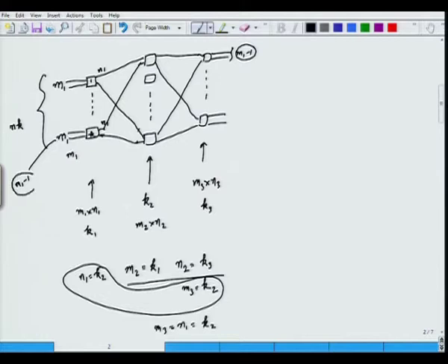the same is true at this place, that M1 minus 1 lines are occupied here. There is only one line which is left in which I am interested. I want to connect these two. In worst case scenario, out of these lines which I am putting here, M1 minus 1 are already occupied. They might be using certain middle stage switches for connecting to some incoming ports. From this side, in worst case scenario, these can be using a different set of switches, there is no overlap between them. If I had one more extra, this can always be used to set up the path between this free input and output link, and the switch will always be a strictly non-blocking switch.